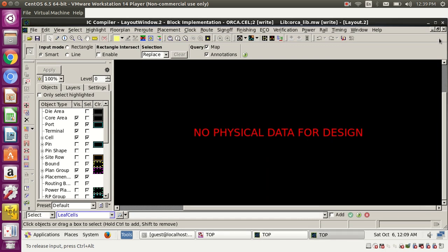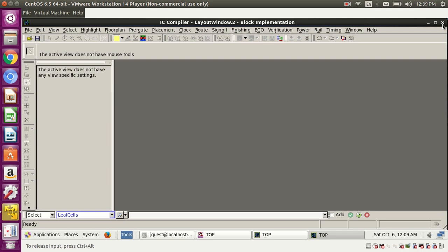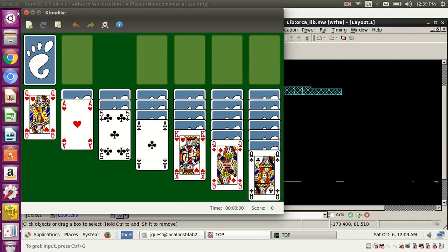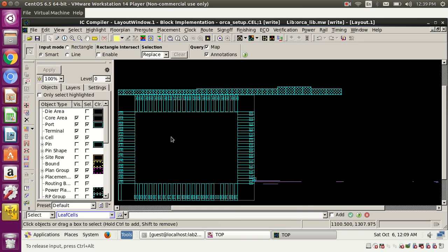These two nets have to be parallel at some point. Suppose net 1 is the clock net, and the shape is going from M1, M2, M3, M4, and M5. Suppose it is going here, and we have net 2, which is the data net. If it just goes from here to here, it will not cause any SI, as you know, if only this portion is touched. But if net 2 is crossing like this, then only it will cause crosstalk.